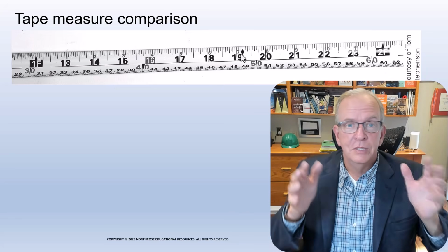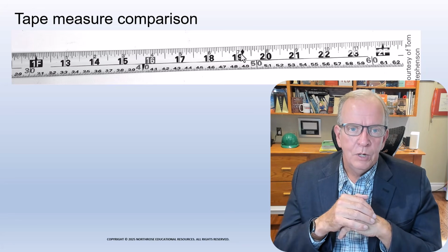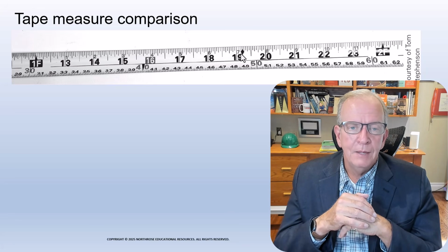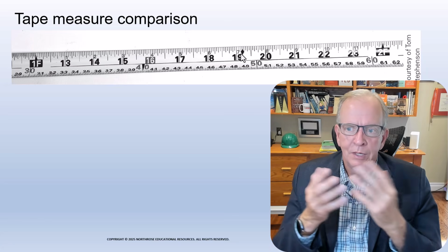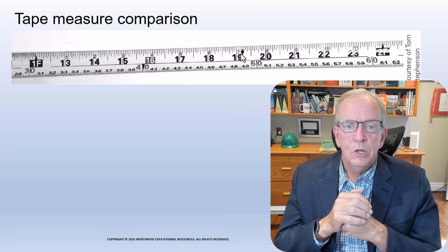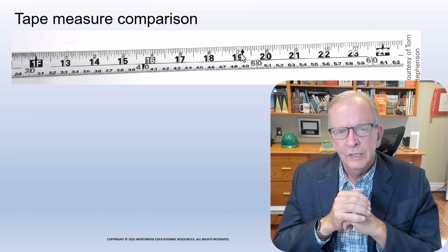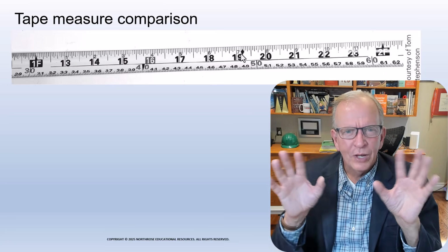So you put all these things together, that's what you would call optimum value engineering, where, yeah, you're saving some money, but you're also making a more energy efficient house. You're not structurally compromising it. Like when you consider we used to build with 2x4 houses, we're building with 2x6 houses. So very good concepts. There's these little concepts that are in and around all areas of construction.